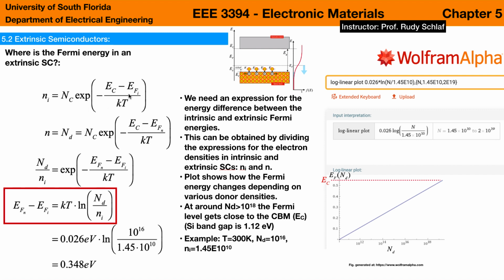So this formula here relates the Fermi energy to the carrier density. This formula also applies for doped materials, except now that we have the dopant density and the Fermi level of the extrinsic material, the extrinsic Fermi level.